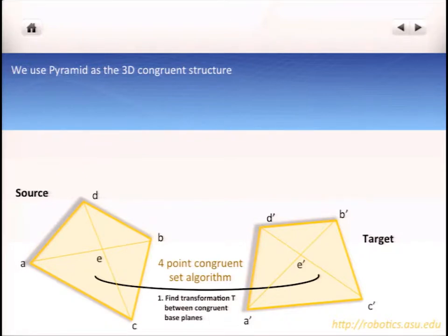Typically in aerial datasets, it is common to find regions with flat topographies. Hence, it is possible to find many false positive quadrilateral base matches. To filter out those false positive bases, we add another point which becomes the apex of the pyramid. Now we have 4 planes which pass through each side of the quadrilateral base and the apex. We call these planes the base apex planes.